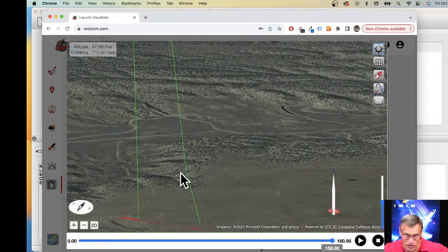Normally it blows through the tube and pushes the parachute out. If there's no parachute in front of the tube because the parachute's already open, the rocket is just hanging under the parachute, and it fires an ejection charge through the tube, and there's nothing in the tube, so it just goes out into the atmosphere.